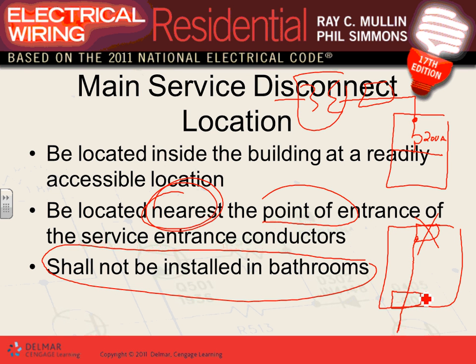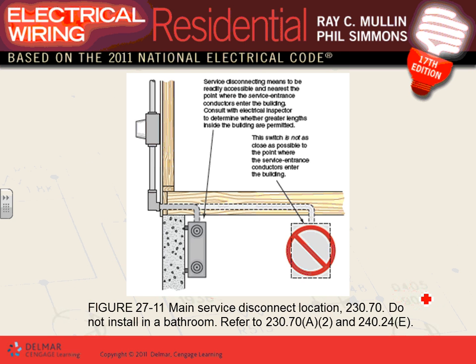Okay, so that's your service disconnect means. What is a service disconnect means? It's the circuit breaker inside the main panel. Okay, here's a good example. You're coming with service entrance conductors into this panel. Here's my circuit breaker right here, my 200 amp panel.